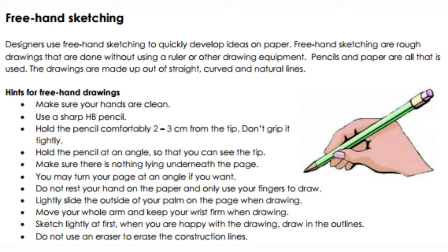Do not rest your hand on the paper and only use your fingers to draw. Lightly slide the outside of your palm on the page when drawing. Move your whole arm and keep your wrist firm when drawing. Sketch lightly at first. When you are happy with the drawing, draw in the outlines. Do not use an eraser to erase the construction lines.